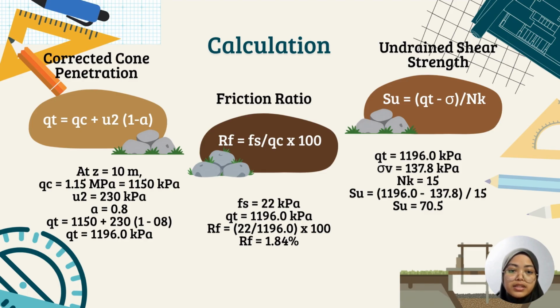High pore pressures, such as slow drainage, and potential long-term settlement problems. The friction ratio decreased from about 3.6% near the surface to around 1.5% at greater depths. High friction ratios are associated with organic and very soft soil, while lower values indicate stronger and denser soil.